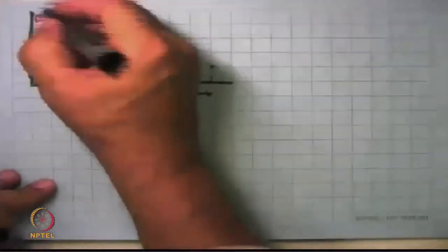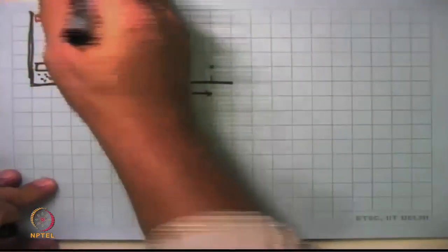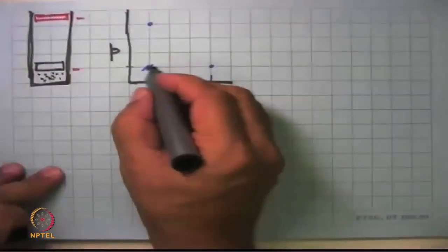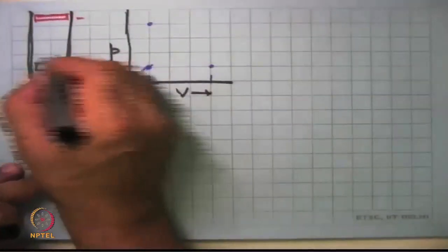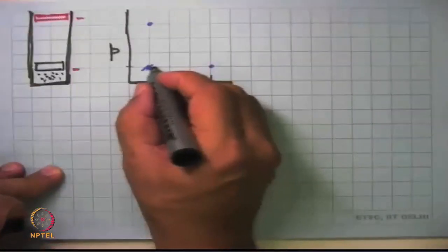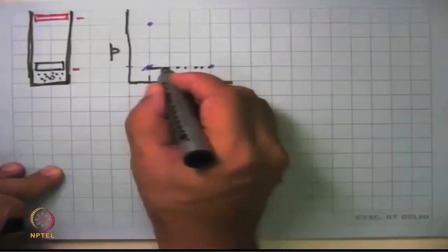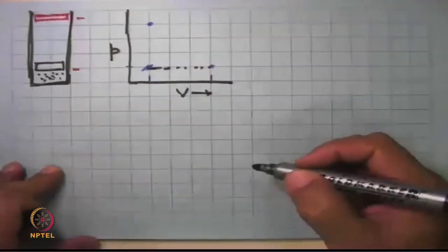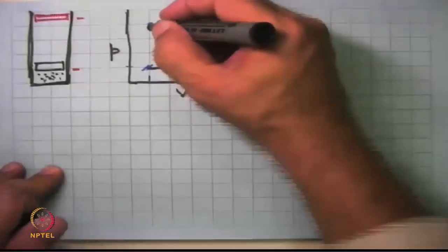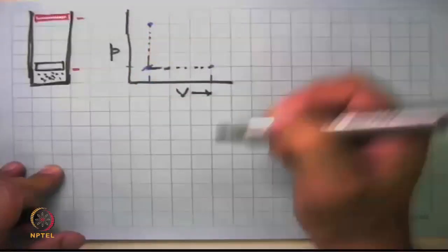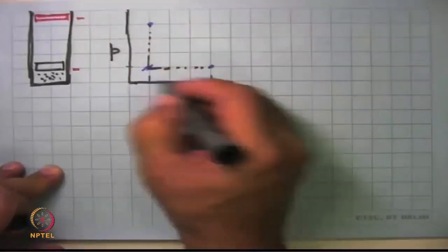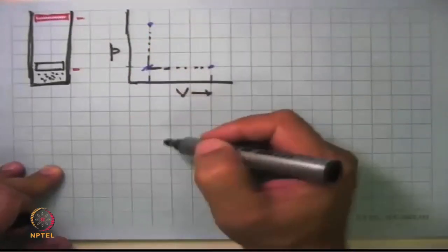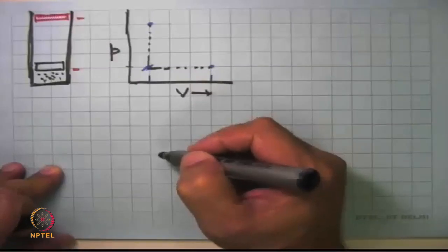the piston does work pushing the atmosphere out, and that's the only work it does. And so the work at any instant, if we were to take it, we cannot do that because it is not a reversible process. We show that change of state by a dotted line. And the work that is available here is the area under this curve. We got only that much work.